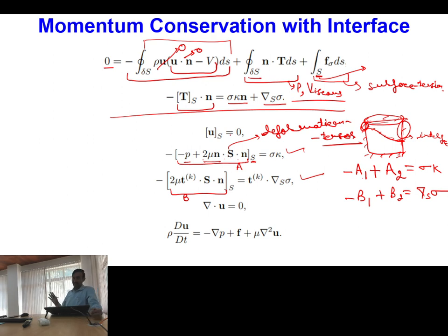So it means that in case of two fluid approach, for a system which is not involved in heat transfer and is of incompressible nature, I will be separately solving continuity and momentum equations for each fluid. Point is clear?